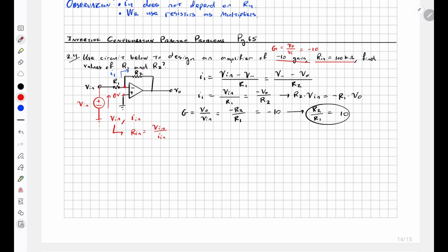Now, in the case of this circuit, we can clearly see that if I apply this test signal, a current goes through this R1. Then there's a virtual short circuit due to the ideal op-amp, and it connects back to ground.